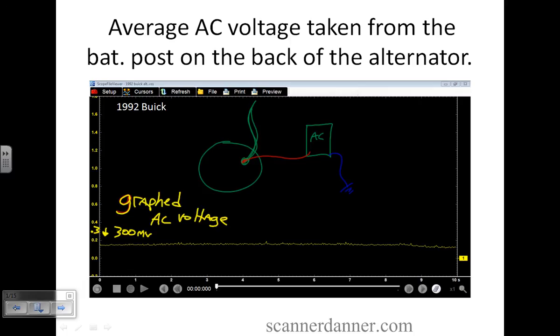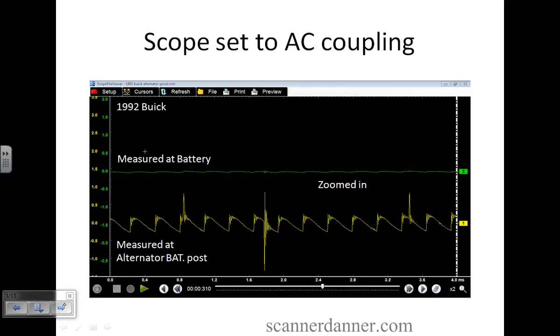All right, so as you're learning this, depending on what you're doing, you'll read material that says less than 300 millivolts. And you're looking at this waveform here. What are we seeing? Look at this spike here. The value of that is -1 here, and +1 is here. So that's at least a 2-volt spike in that waveform. Wouldn't this pique your interest if you're first learning about this? Wouldn't this make you say, hey, there's a problem here with this diode, I may have a bad alternator, and if you're reaching for a cause of a particular symptom, you're going to grab onto this.